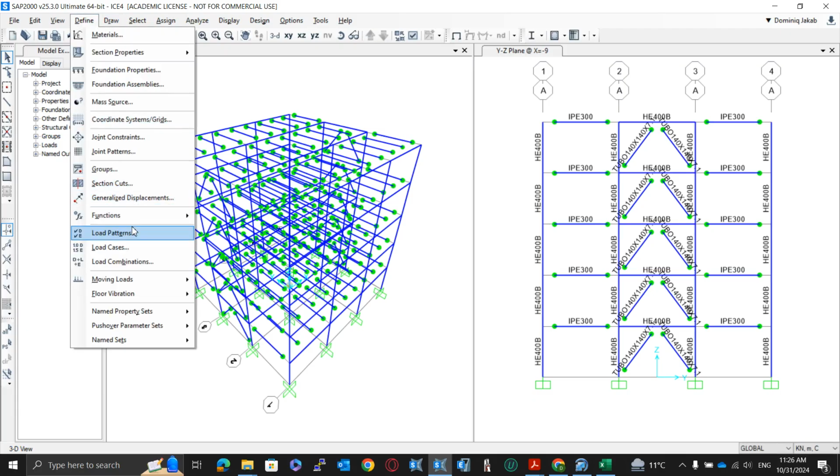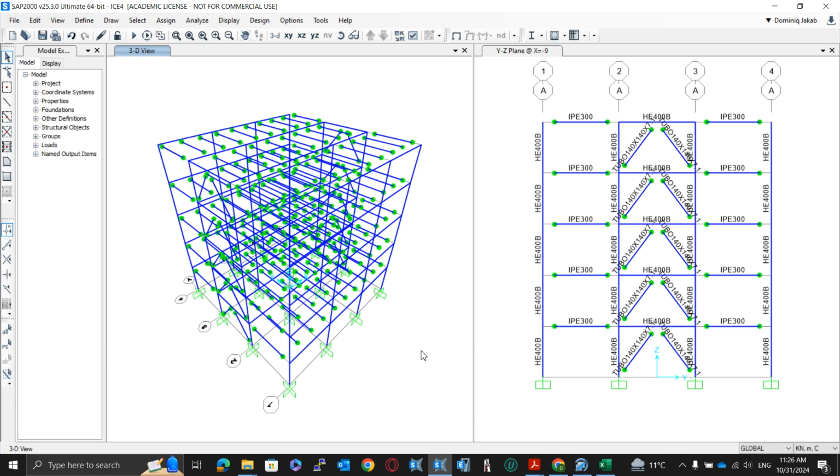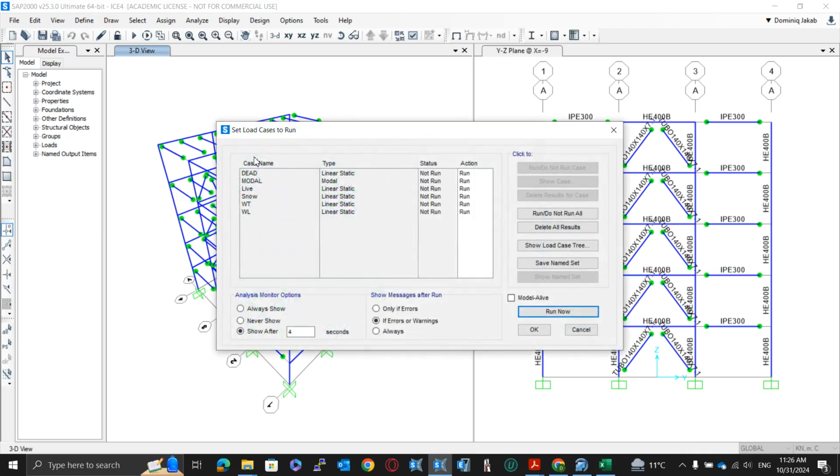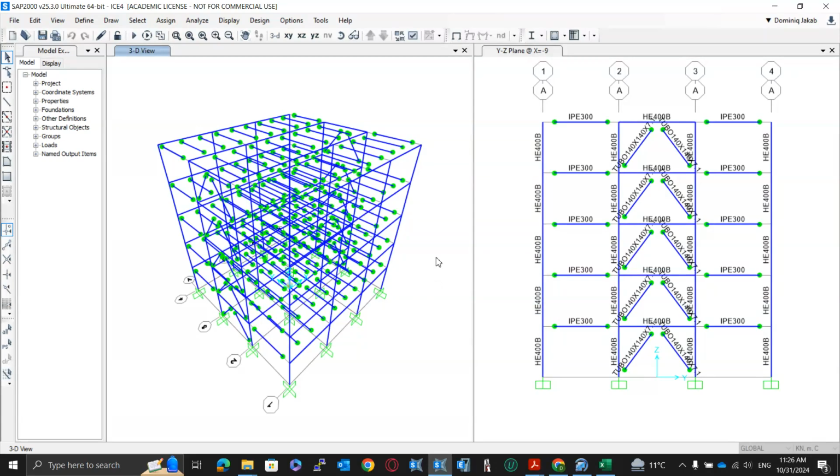And we can check, let's say, the modal response to see the periods and so on and so forth. We won't perform the design. I want to discuss restraints, and then I will show you imperfections and second order effects. Now I will save, and the modal case is defined as default by the software, so you need not define modal. You see here the modal case. Now I will run it.